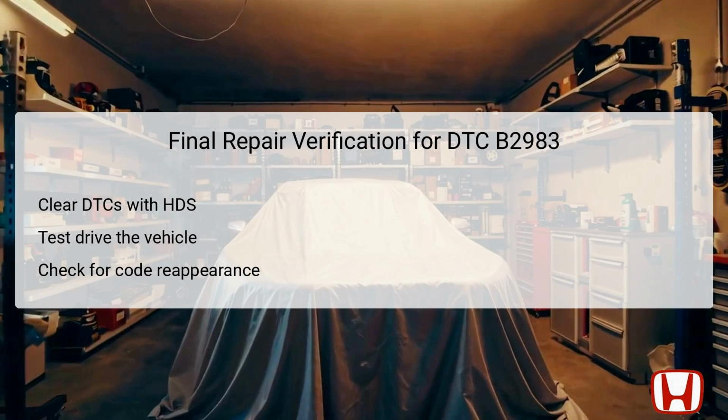After completing all necessary repairs, it is crucial to verify that the repairs were successful by clearing the diagnostic trouble codes using the Honda Diagnostic System, HDS. After clearing the DTCs, it's advised to conduct a test drive to ensure the system operates correctly and maintains the appropriate climate settings without triggering the DTC B2983 again.